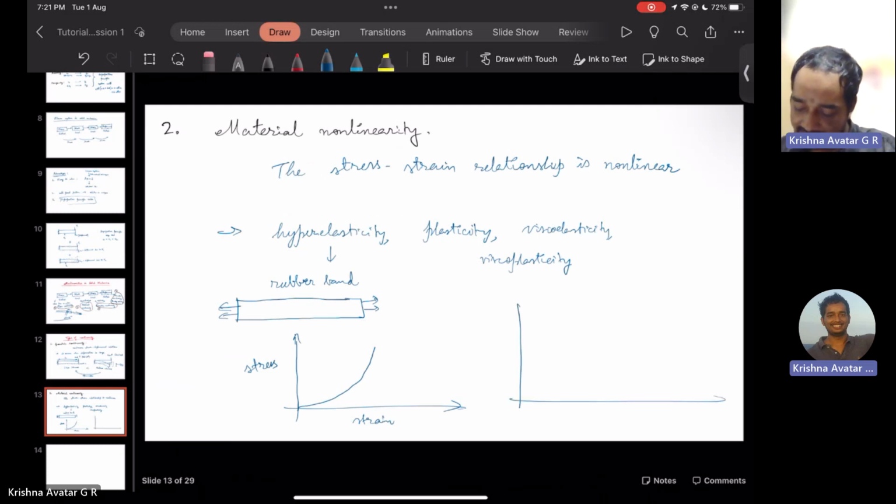Let's just discuss it. You must have read about the stress and strain relationship for an aluminum object, right? You have an aluminum cylinder, and some material test, some load testing is done, and you see that there is also a necking phenomenon. So it's linear to some extent. Then it reaches the yield limit, proportional limit, right? Then there is some necking here, and ultimately it just fractures, isn't it? So you see that the linear relationship is only to some extent.